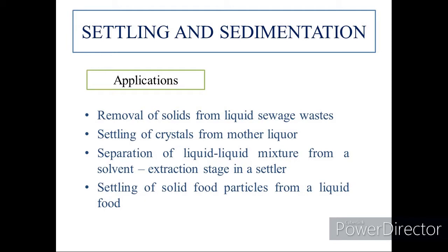Some of the common applications for settling and sedimentation are the removal of solids from liquid sewage wastes, settling of crystals from mother liquor, separation of a liquid-liquid mixture from a solvent extraction stage in a settler, and the settling of solid food particles from a liquid food.